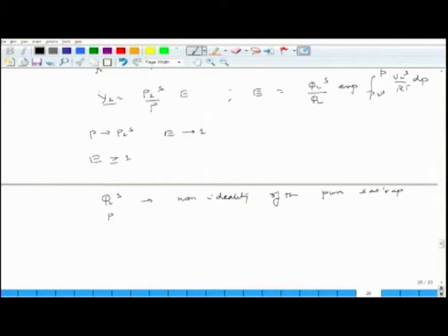And the Poynting correction, of course, we all know is the pressure effect. What is phi 2? This is the vapor phase fugacity coefficient in the high pressure gas mixture, right. Because it is dense, the pressure will be very high. It is not a low pressure system at all.